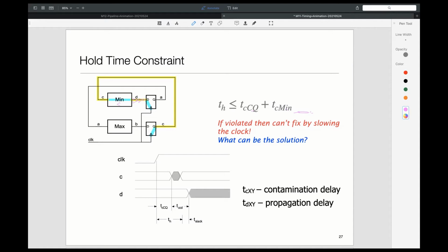It sounds easy. It's a little bit tricky. Firstly, when you're adding gates, you still have to make sure that all of this will keep working at all temperatures. Remember, this equation has to hold true across all temperatures that your chip will face. And usually for commercial designs, if you're unlucky enough to be living in very cold places, your temperature could be like minus 40 degrees Celsius, Fahrenheit, whatever, right?